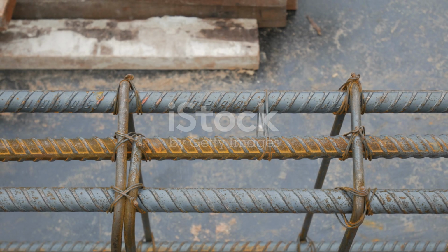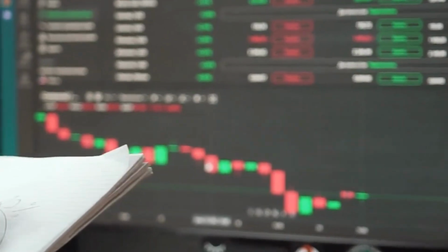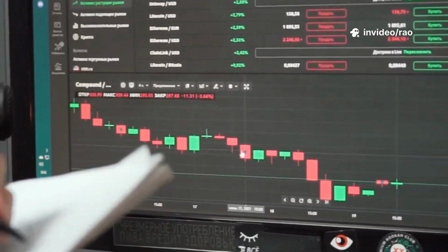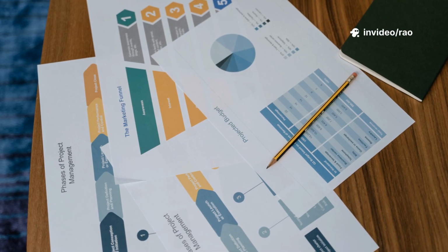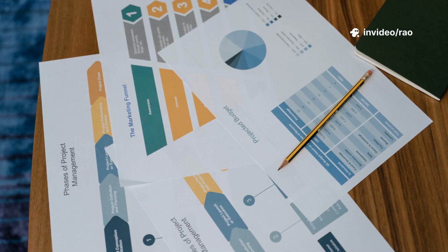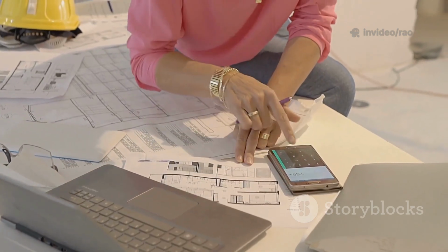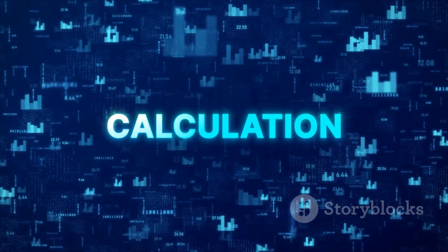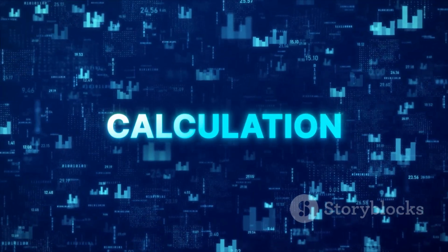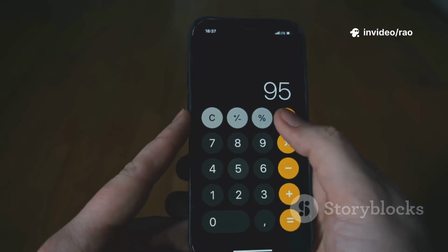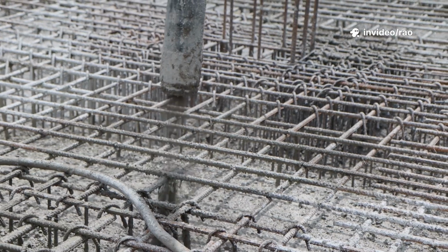First, calculate main bars. Main bar length equals 4 m, i.e. 4000 mm. They run across the slab width. Slab width equals 3 m, i.e. 3000 mm. So total distance equals slab width. Number of main bars equals 3000 mm divided by 150, plus 1. Number of main bars equals 20 + 1, equals 21. We need 21 main bars.